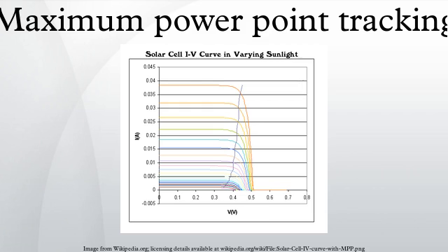Maximum power point tracking is a technique that grid-connected inverters, solar battery chargers and similar devices use to get the maximum possible power from one or more photovoltaic devices, typically solar panels, though optical power transmission systems can benefit from similar technology. Solar cells have a complex relationship between solar irradiation, temperature and total resistance that produces a non-linear output efficiency, which can be analyzed based on the IV curve.